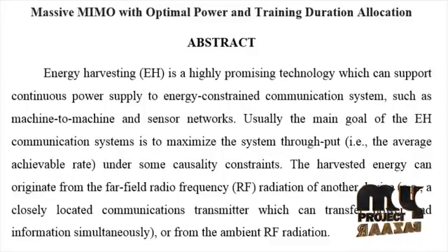Some interference mitigation is offered by limited intercell coordination, which is conventionally restricted to scheduling or user assignment mechanism, or soft handover techniques. Intercell interference is treated as noise at the receiver side and is handled by resorting to improved point-to-point communication between the base station and the mobile station using efficient coding or single-link multiple antenna techniques. Optimal precoding over the broadcast MIMO channel as well as optimal joint decoding over the uplink involve non-linear computationally intensive operation which scale poorly with the size of the network.